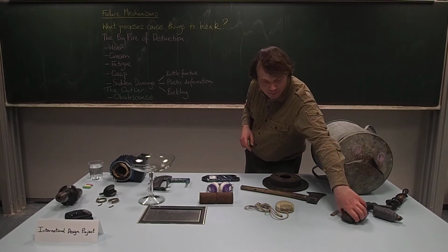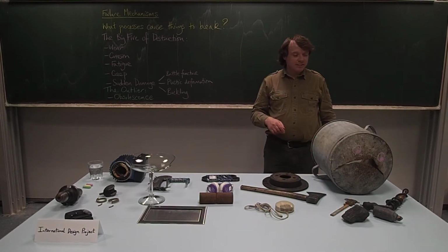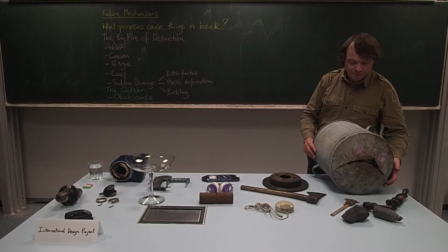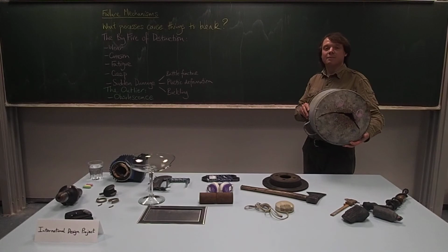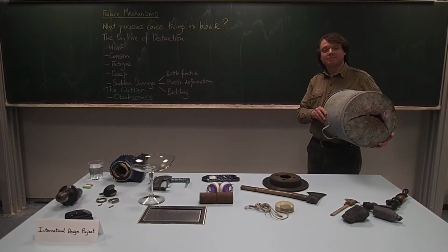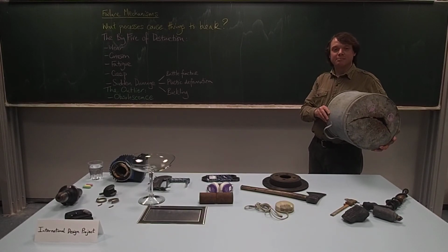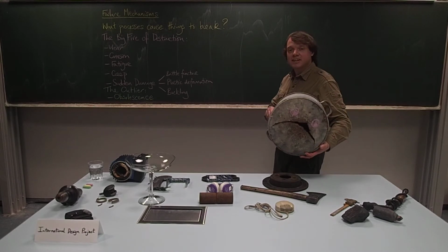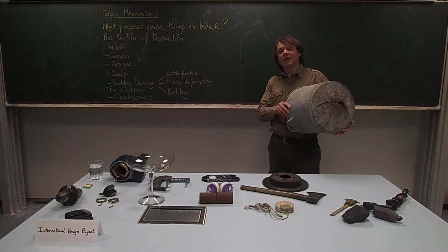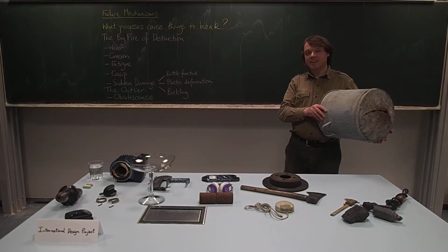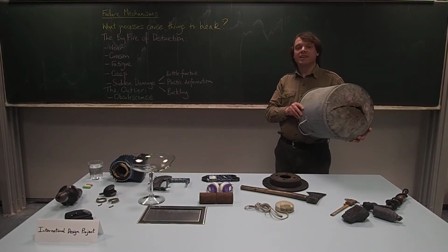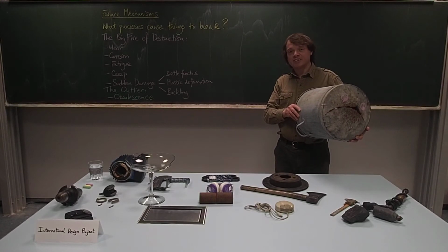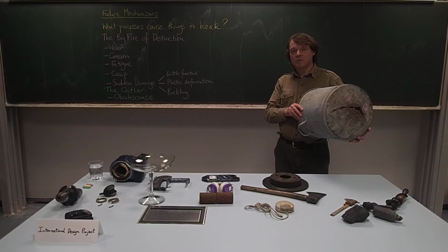Here's an example of something that's been degraded by corrosion. This galvanized bin here has probably had some fallen leaves sitting in the bottom of it, maintaining some dampness. And then you've had wet corrosion, an electrochemical process, slowly eating away the iron at the bottom and turning it into iron oxide, which is then weaker.